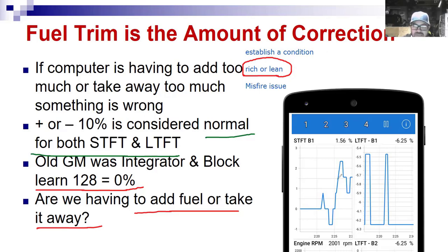So here I can see fuel trim for short term on bank one is pretty close to 0, right? He's bouncing around a little bit. He's at 0, he goes up, he goes down a little bit, he goes up. And he's doing that as the engine speed changes. And of course, as the engine speed changes, what does that mean? That means I'm going to different cells in that chart or that graph that we were looking at, right?